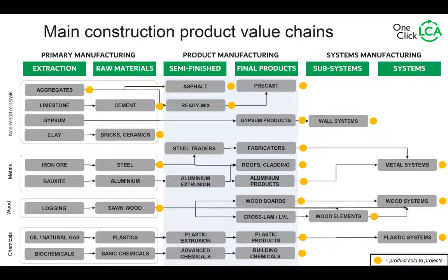However, cement is predominantly used in concrete, and concrete is then used in two or three forms, let's say. It's used as ready-mix concrete, which is poured in a fluid form into a mold, and in a precast form where the rebar is already placed in the mold, and the product is left to cure in a factory.